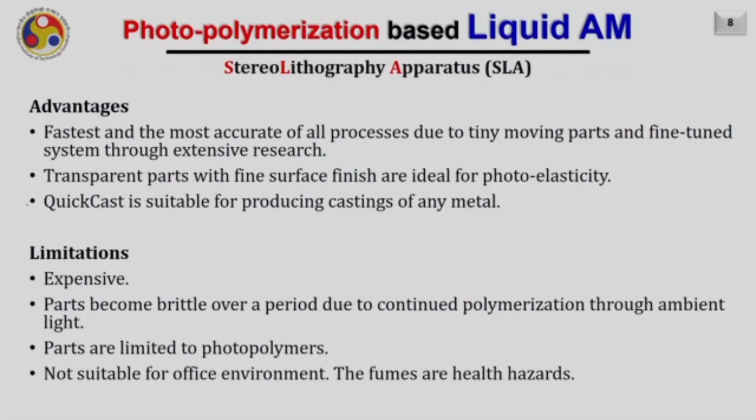Also, another benefit of this process is that you can make the pattern for creating the casting. 3D Systems SLA gives a particular name to such patterns and calls them QuickCast. These QuickCast patterns can be further used to create the shell around, and then an evaporative casting process is used.